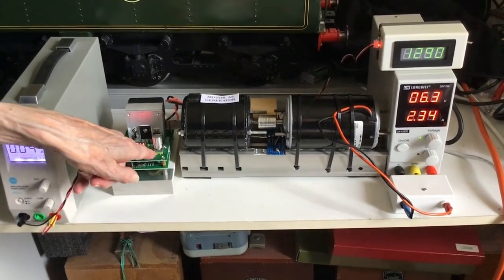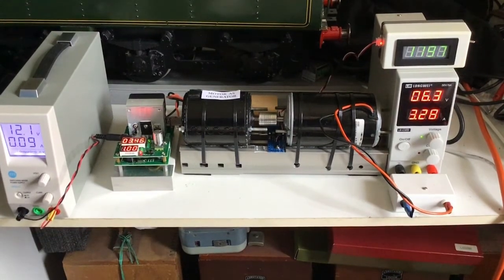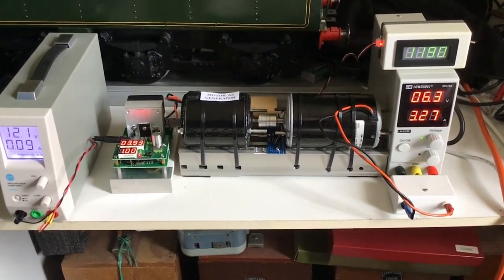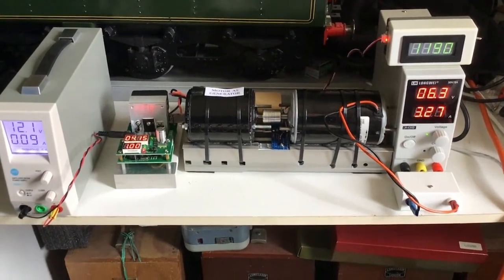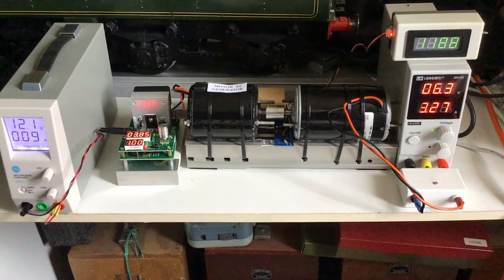When the load was applied, the speed fell to 1188 rpm, a drop of only 8.3%. As Vg fell, Vrm, which is Vs minus Vg, increased, and therefore increased the motor current Irm, which in turn increased the torque to partially compensate.